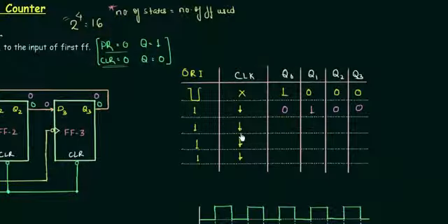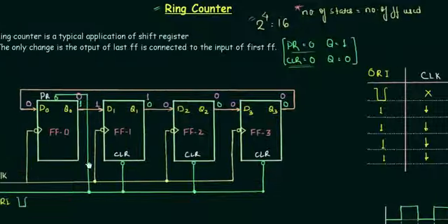In the same way, we will do the analysis of the second falling edge quickly, and we will try to find out the inputs first. Here we are having 0, so D0 is 0 again. This is 0, so D1 is 0. This is 1, so D2 is 1. This is 0, so D3 is 0. We have our inputs. This brown one is the input now.